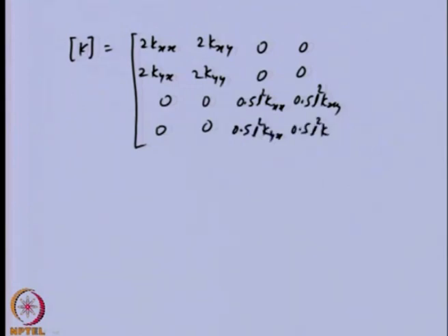These cross coupled terms were not there earlier, only direct stiffness terms were there. So, in the previous lecture, we had these diagonal terms. Now, these off diagonal terms are coming into the picture. Basically, these off diagonal terms are getting multiplied by the linear or translatory displacements, so they are coupling the motion in 2 directions, and these are coupling the tilting motion in 2 directions,